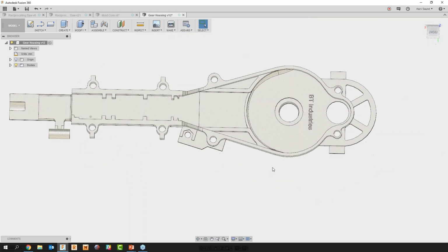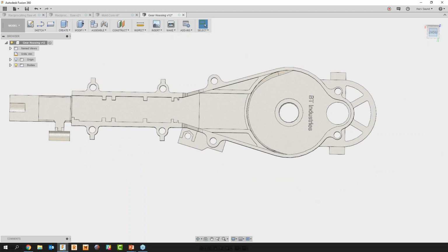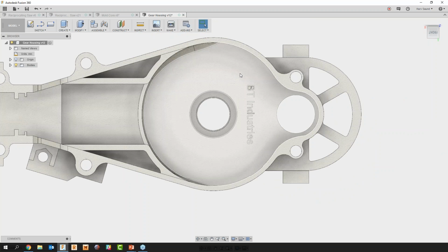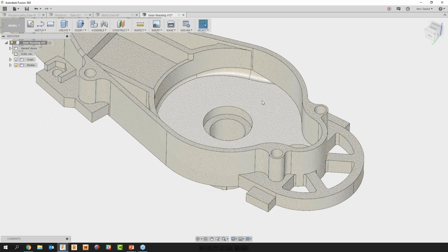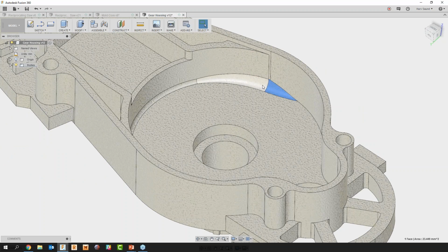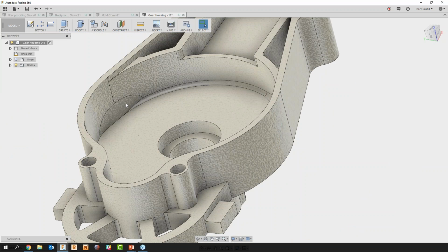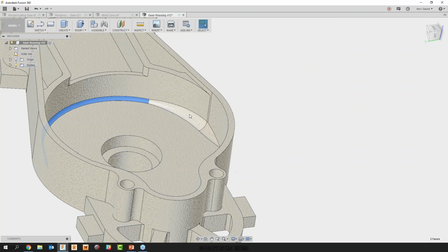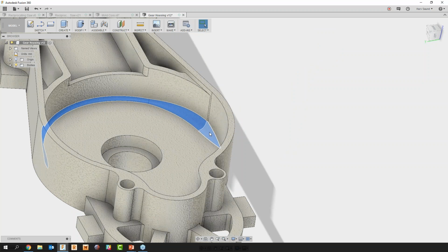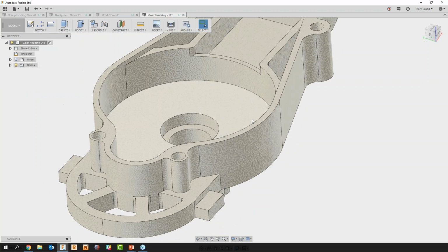Now, because we're going to manufacture this in-house, we don't actually want the previous manufacturer's logo in place. So what we can do is just highlight their logo, and again, using some very detailed tools within Fusion, delete that out. This is using what we term direct modeling. So in effect, in Fusion, what we have is the 3 paradigms of modeling: direct, freeform, as well as parametric. So it gives us the ability to give you guys the tools that you need to manipulate and change those designs exactly as you need to.